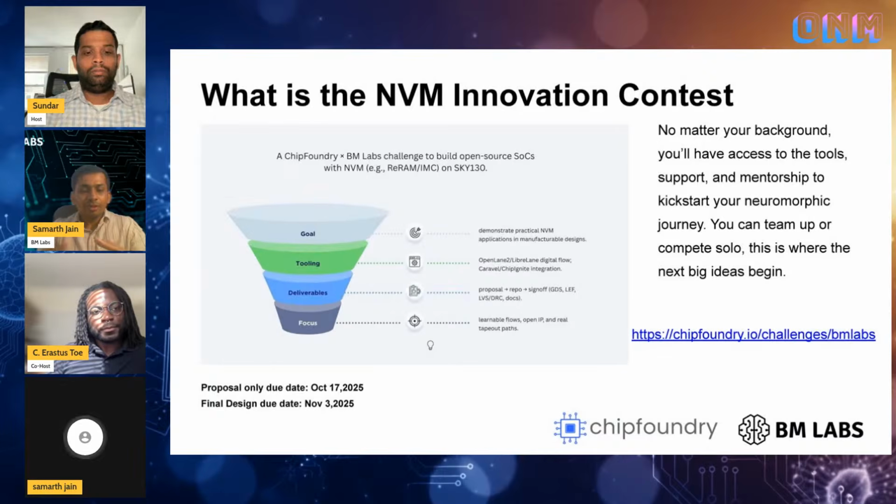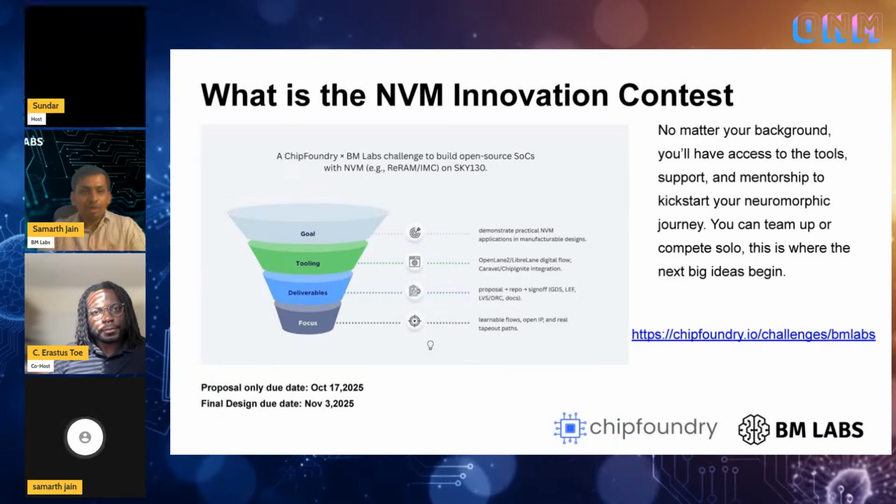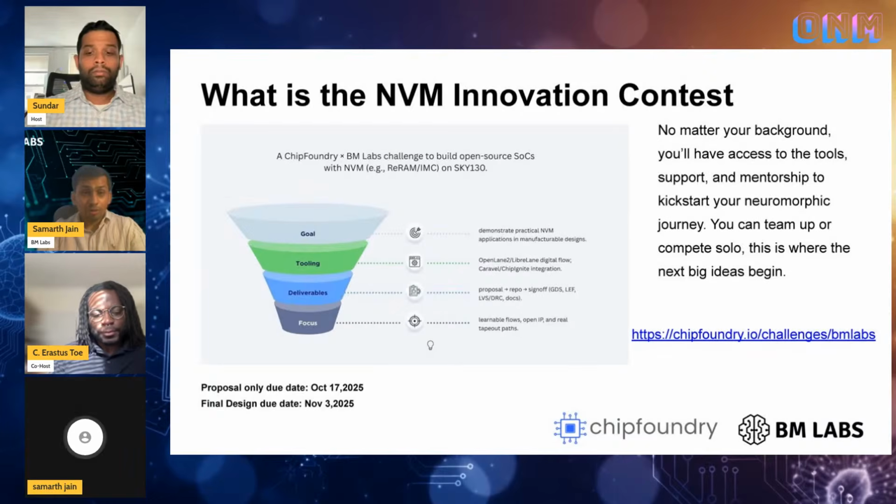So just write your behavior level Verilog and validate it using CocoTB, which I just showed you, right? Use that tool to verify whether your design makes sense. Once your behavior model is ready, convert it into Verilog, and then use OpenLane to make sure that the Verilog can be manufactured. So you have to go through some iteration using Verilog and OpenLane, right?